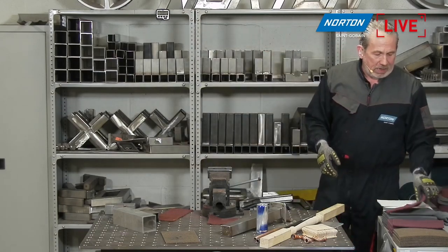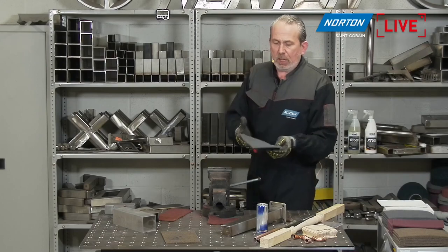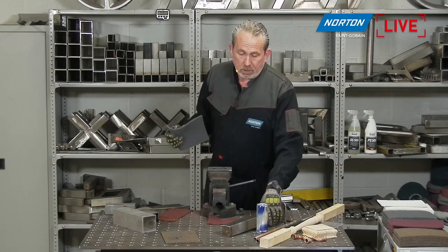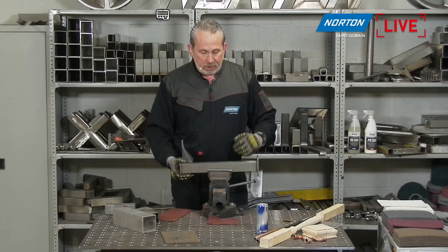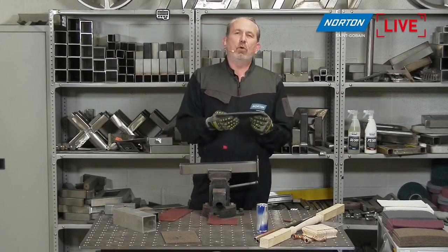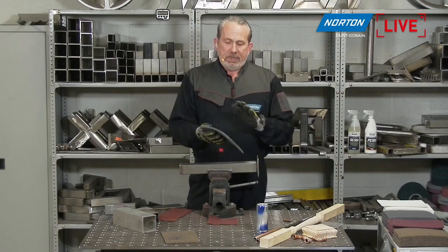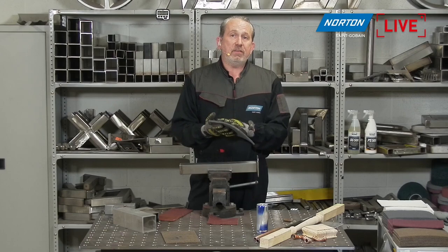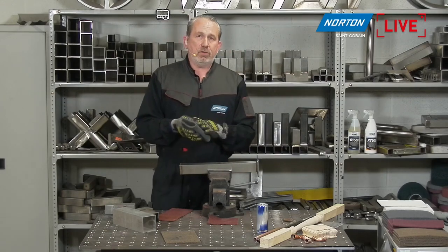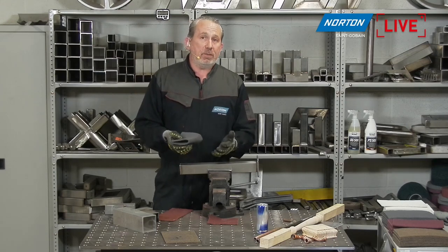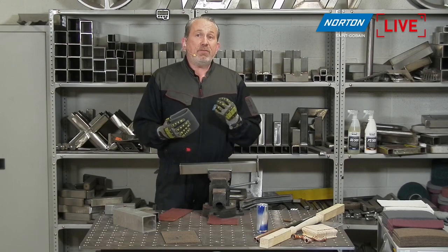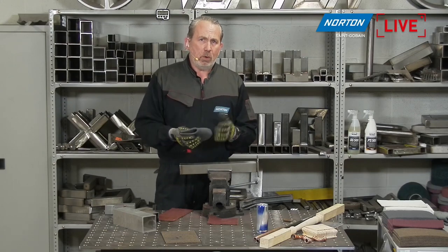Next product we're going to have a look at is our silicon carbide very fine product. Okay, I mean, we can bring back the steel balustrade we had earlier and give this more of a finish, because this is more for final finishing. Inside here, we've got an ultra-fine silicon carbide grain. On stainless steel, that works really nicely, giving us a much brighter finish than the aluminium oxide grain, which are in all these other products. It'll give a much brighter finish on stainless, so it just pops out a little bit more.